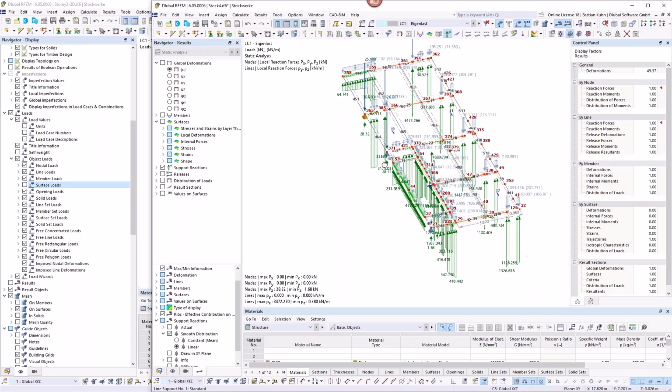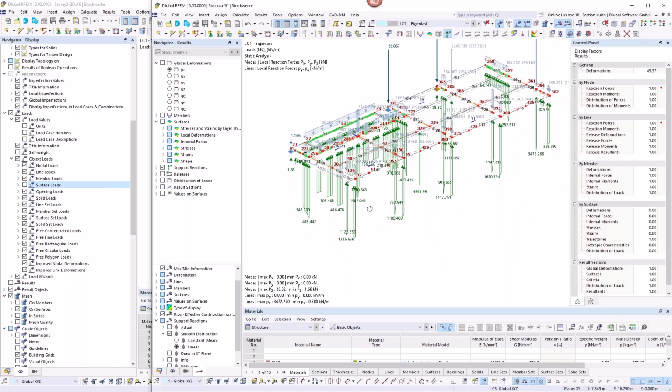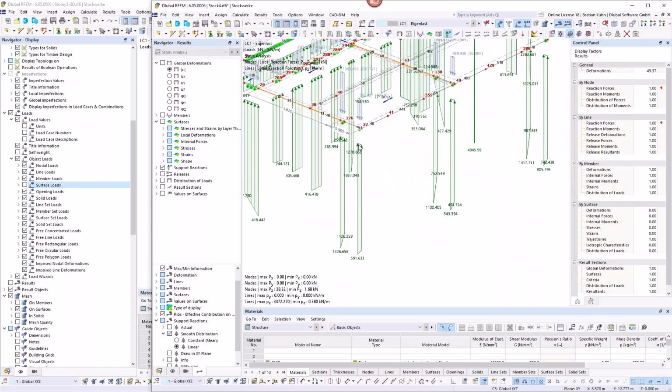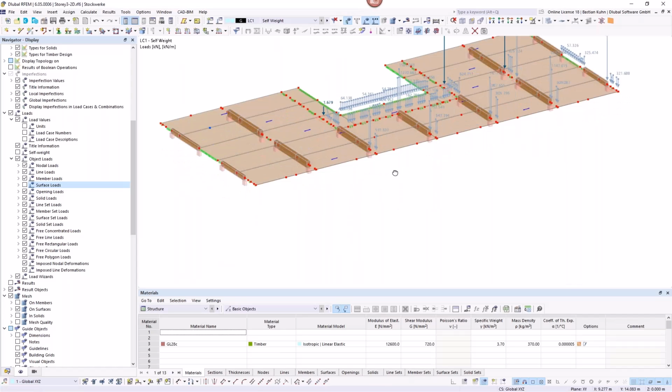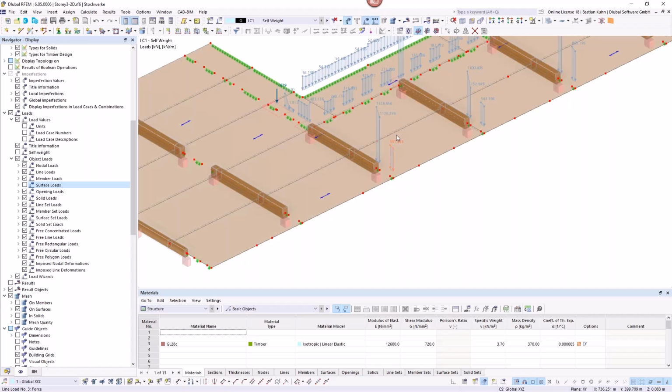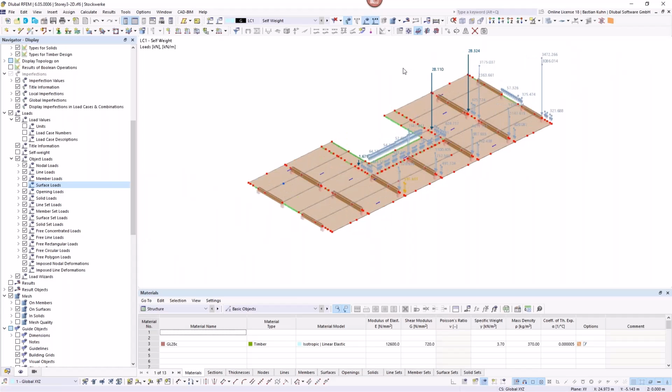So that really is the load transferred from this model into the other. And maybe we also take a look at the line load here. So 591 here, and then I think it should be enough. And right here, you see also 591. So yeah, that fits. The load is correctly transferred from, I would like to say, story 13 to this part that we are analyzing here.